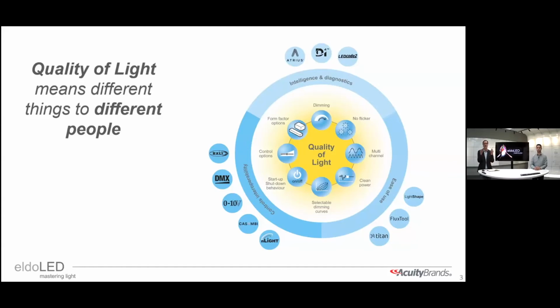Well, these are basic elements, but for now, we talk about human-centric lighting, which I would say is the next step if you start talking about dimming or color control or anything else. Yeah, color mixing is basically dimming two channels. So it is not dimming one channel, but it's dimming two channels in such a way that we get the right perception of either color temperature and intensity levels. But in essence, it is still dimming, just pronounced and controlled in a different way.